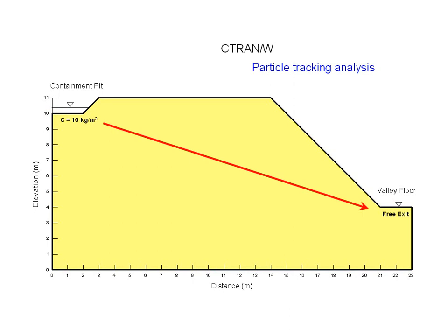The first CTRAN/W analysis will be a particle tracking simulation, which is a quick way to determine the extent of the contaminated region by simulating how individual particles would move through the soil profile with time. The second simulation will be an advection dispersion analysis, which will model the concentration of the contaminant plume as it advances through the profile with time. Chemical diffusion is considered inconsequential and is ignored in this particular analysis. It's assumed for this tutorial that you are already familiar with the GeoStudio environment. If you've never worked with GeoStudio before, you may wish to first review the Getting Started tutorial for SEEP/W.